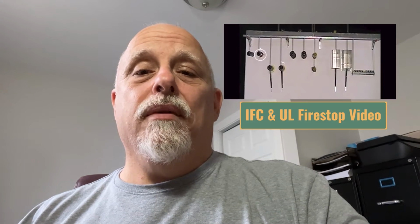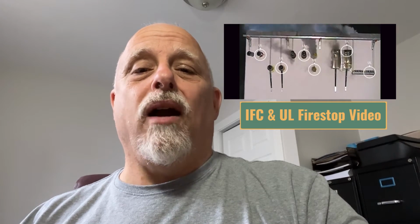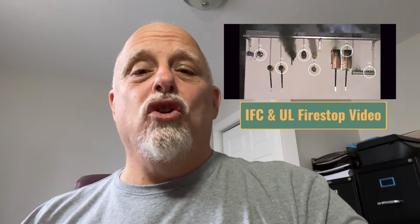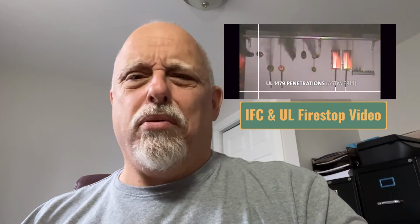Now, the NRTL has specific laboratories, and there's actually a really good video on this. If you go to YouTube and you type in the search bar IFC UL firestop, you're going to find a video on how they actually test these systems. Pretty cool. So if they design that system for a 2-hour rated system, they're going to put it in that burn box and they're going to burn it for 2 hours. Now, there are some additional tests that are required based on what region this is done in, and this is not a cheap process. Some of the firestop manufacturers, like Hilti, have their own testing facilities.